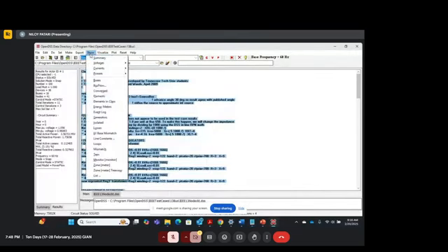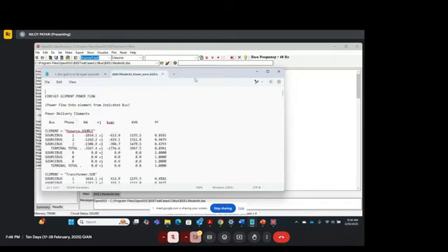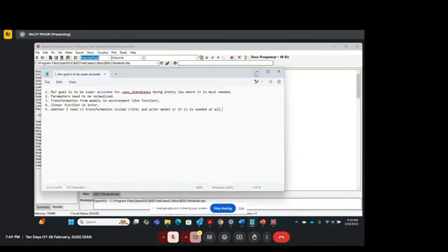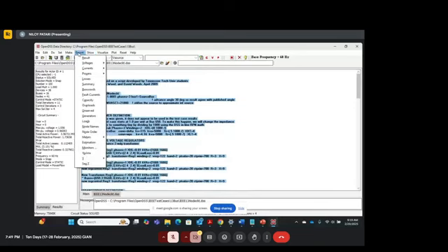And what else? You have energy meters, you have taps also. Here you can check the taps. So the taps are kept at 9, 6, and 9. If you remember, these tap positions don't match with the IEEE test case results, right? So we will try to see if we match the positions, does power flow hold or not. I'll come to that as well. So under the show button, you can see all of that. But you can also export the same data to a CSV file.